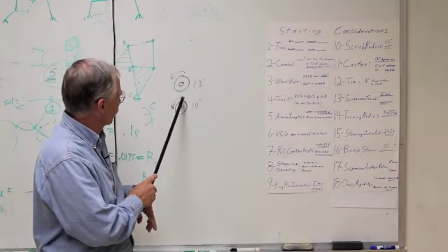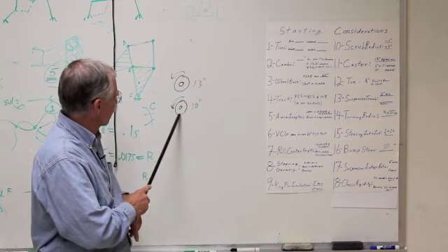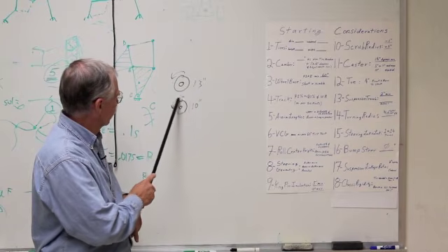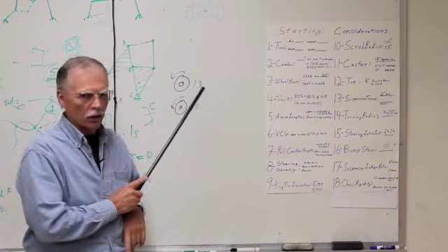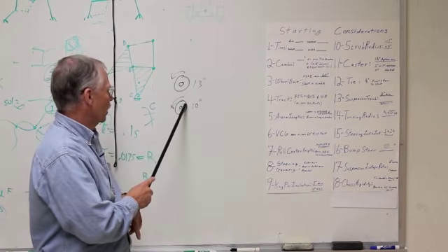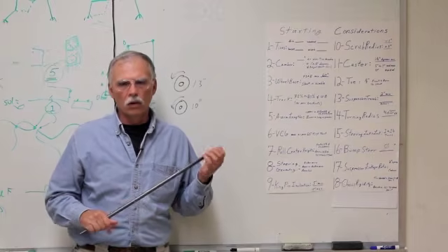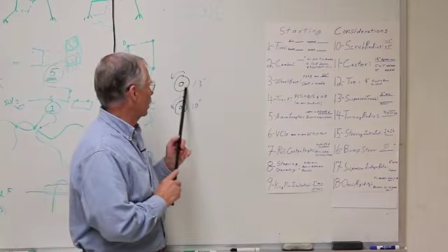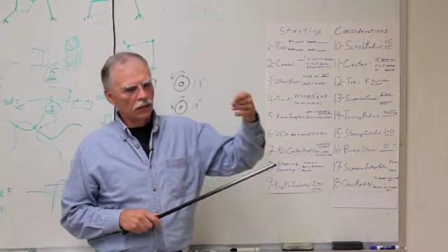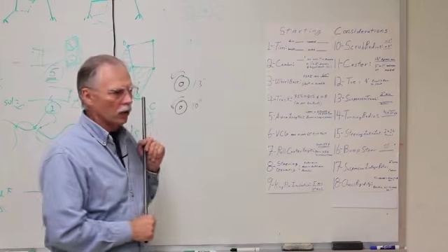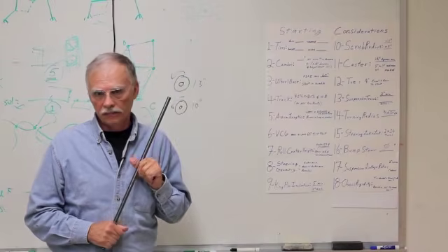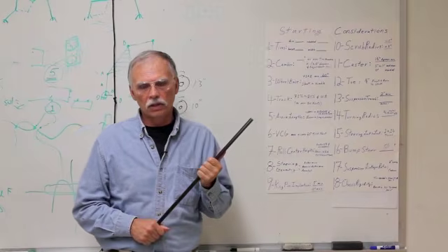Because its circumference is less, and so the heating cycle, which takes place at ground level when the tire rotates around, comes around in a shorter time window per mile travel. So a 10-inch tire will run warmer than a 13-inch tire, which means it will be up closer to its best operating temperature. It also is lighter, and weight is a big consideration on these cars.